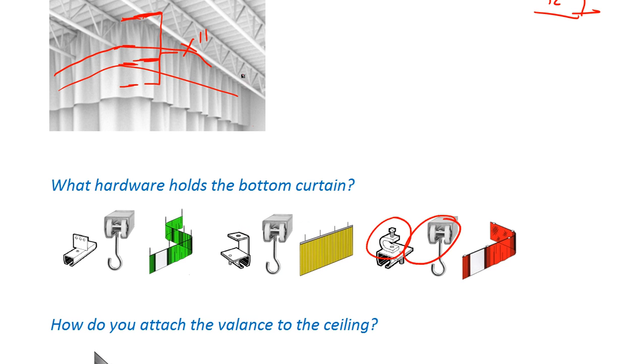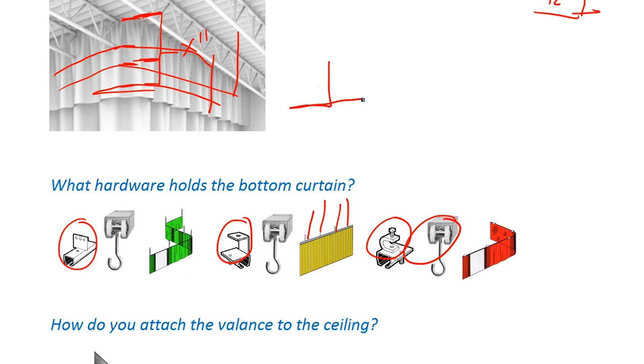If you want to drop down, for instance, you're dropping down off of the joist and then putting our hardware down here, then you'd use a threaded rod style, or you could use a chain or cable. So with threaded rod style, you would also use an edge clamp, which would clamp onto the flange. And let's assume this is an I-beam. The way the edge clamp works is it goes around it, and it has a set screw right here, and it pinches the flange.